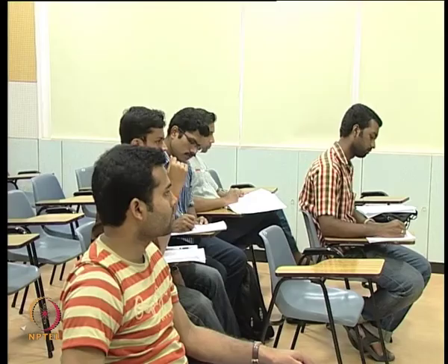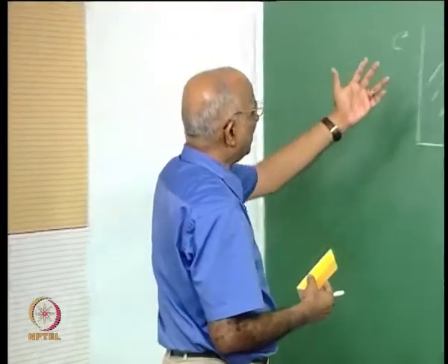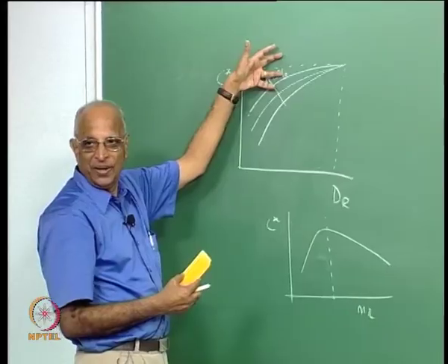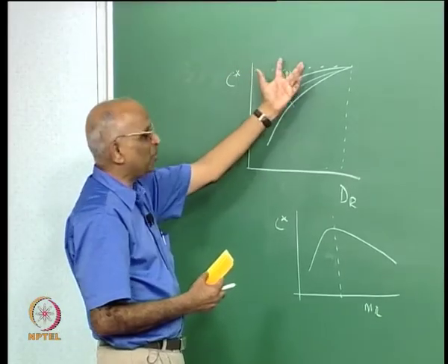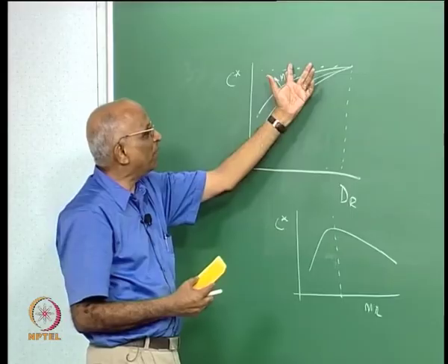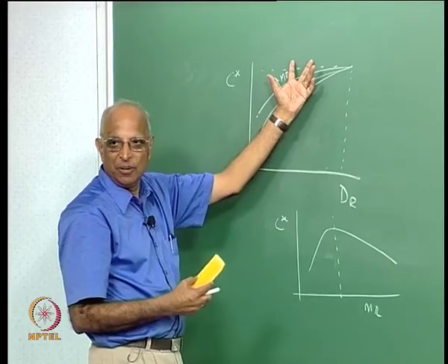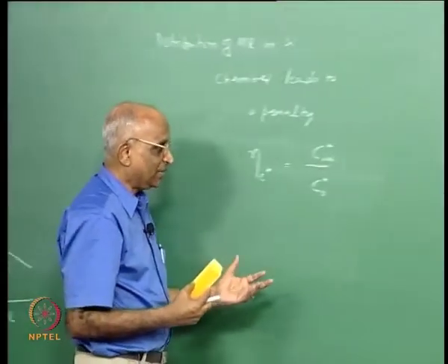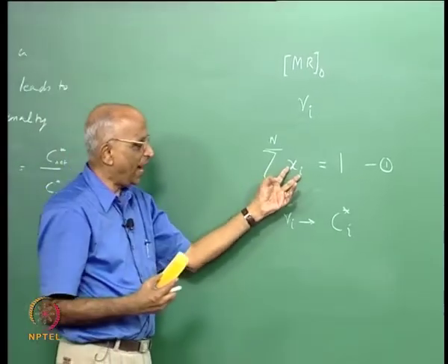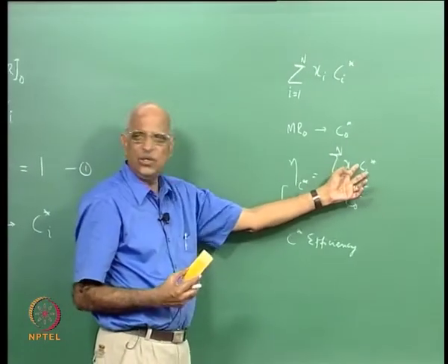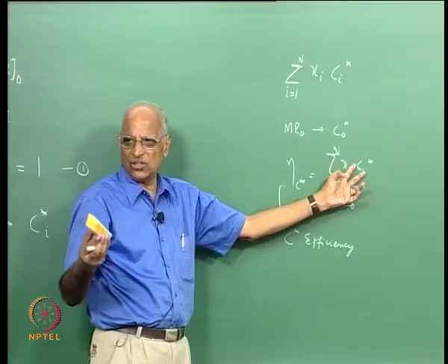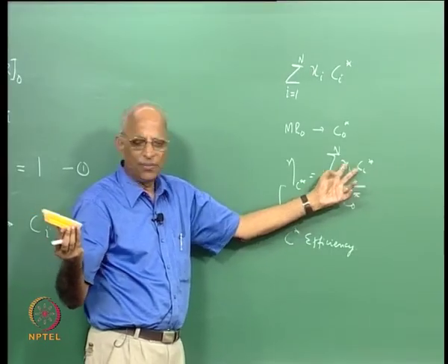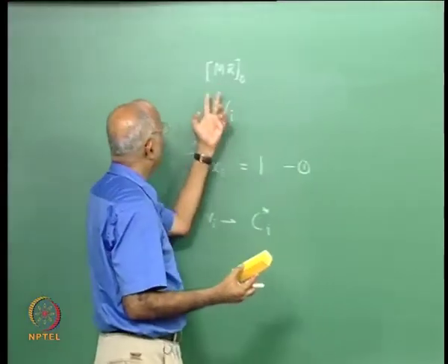Can I restate your question? You want to know how to determine the distribution of mixture ratio. Well, you know the injector, the type of injector you use, you know how it is forming droplets, you know the distribution of droplets at the head, you know what type of droplets of oxidizer and fuel are coming, because your concern is how do I estimate the value of, let us say, xi for each of the stream tubes and the value of Ci. Ci you know anyway, because you know how C star varies with mixture ratio. The only thing you need is the value of xi.